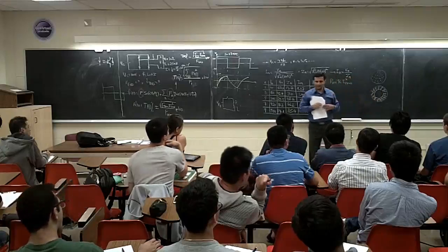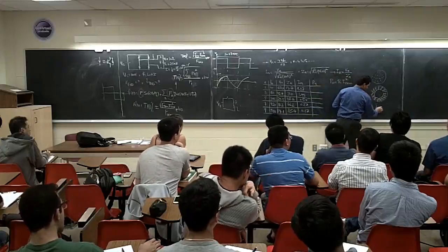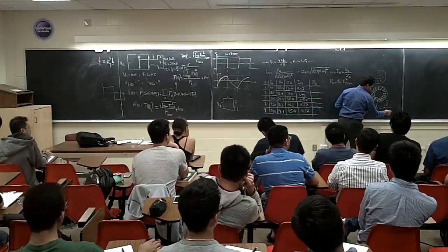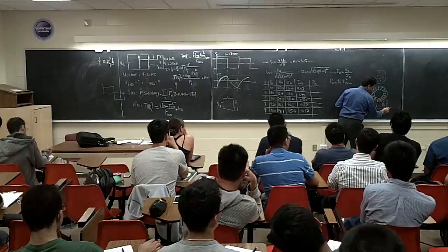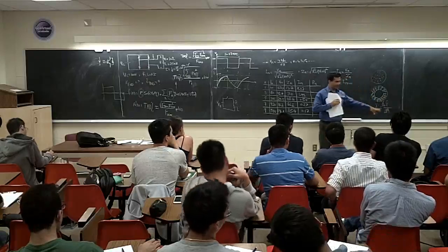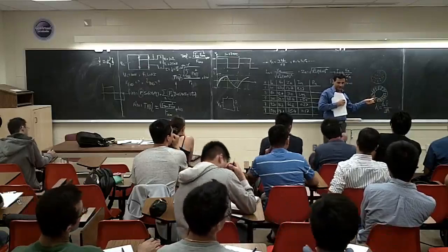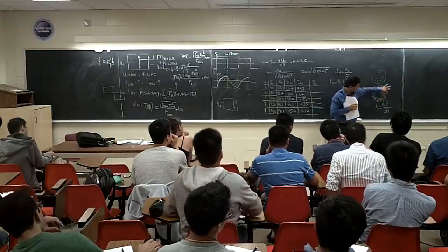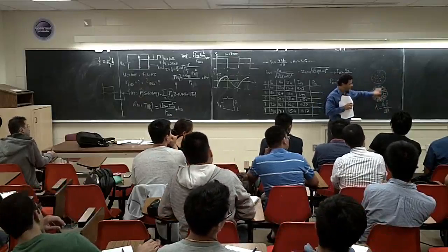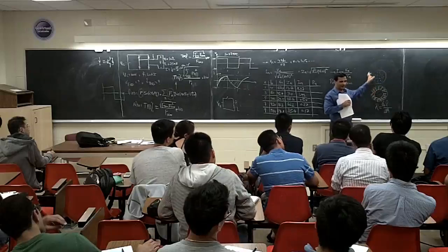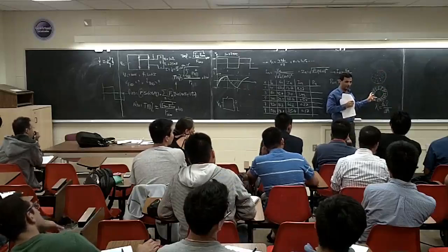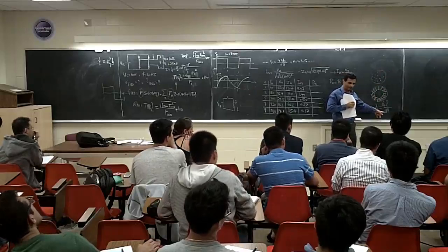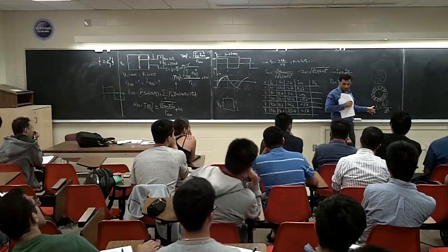Basically, the resistance is L over sigma A, or sigma L A, I can't remember. I think it was like this, right? In this AC case, how much is A? It is this area. In the DC case, A is here. So you can see in this case, A is smaller. A is smaller means the resistance is bigger, right?